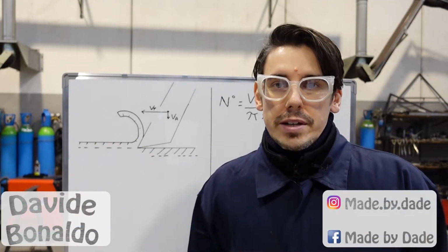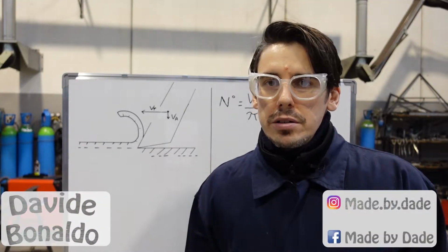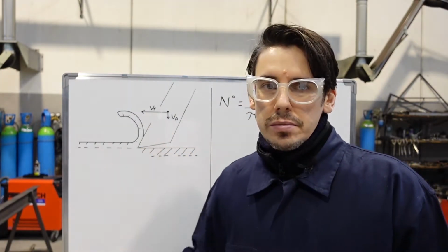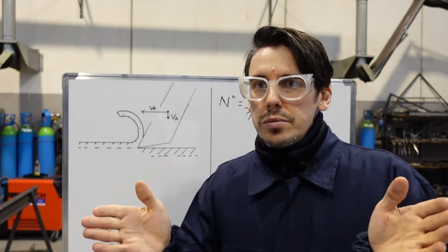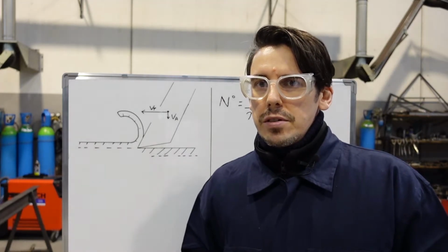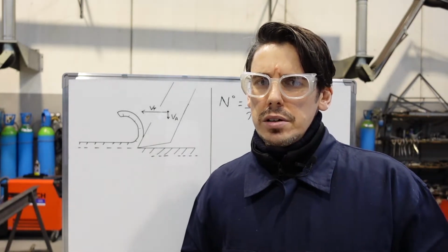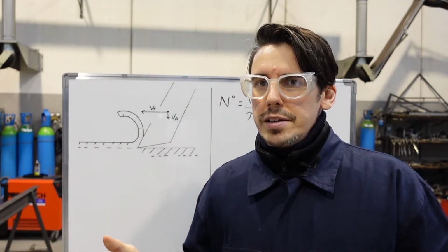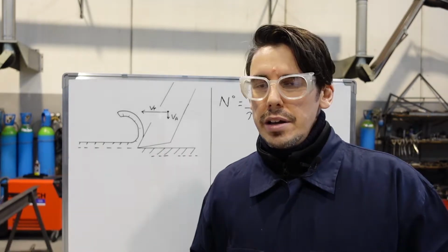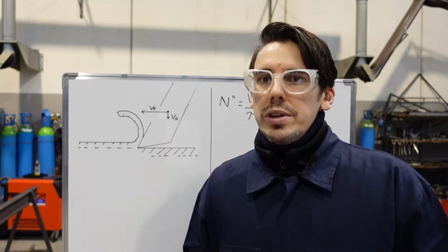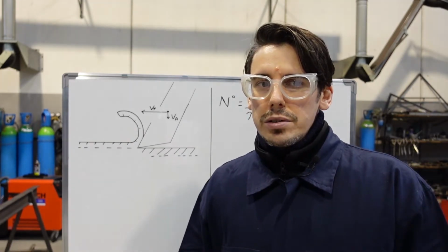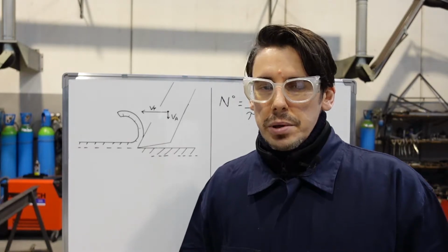First of all, what is cutting speed? Well, cutting speed is nothing more than the space that the tool travels in the material in a given period of time. Generally, this value is expressed in meters per minute. It's generally found as a parameter in the table provided by whoever sells the tools, and is indeed a theoretical number, an optimal value, but I would like to make you understand specifically how it varies in order to adapt it to reality, because it's the final goal.